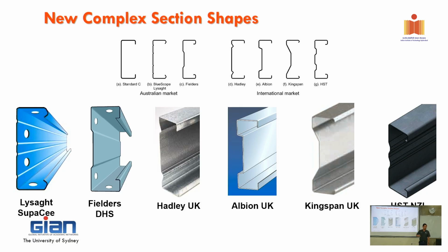So the way that they can improve that, because yield strength can't be improved, right? Yield strength is already good, 600, 550. If you thin the section and use the effective width method, it just goes up to 200 or 300 and it buckles. That's what we learned last time, right?